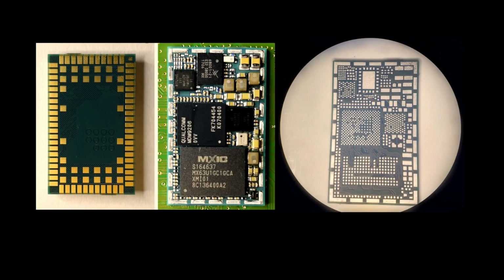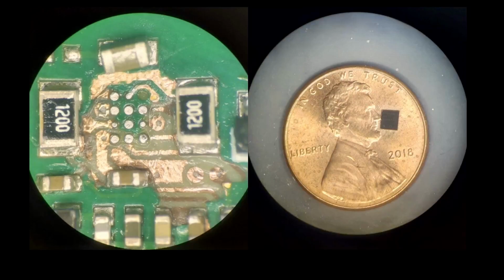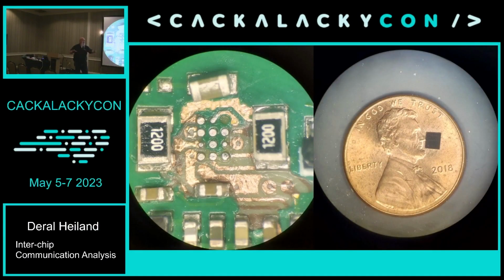And in one case, I was working on something a little more complex where we're dealing with a SAM module, which is a security module. The security module is only 12 pins, and I literally started delayering the board under a microscope, bringing down the layers of the board, trying to figure out where all these runs were since it was a multi-layer board. In this case, they actually thought through this whole process and the potential attack vectors. I was never able to successfully do it. I ran out of time, obviously, but I made it down to like 3 layers there.